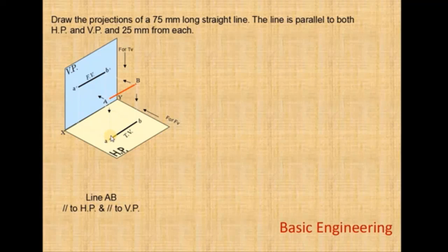And this distance from the HP is 25 mm. The line is 25 mm above the HP. From this line to the horizontal plane is 25 mm. From this line to the vertical plane is 25 mm. The line length is 75 mm. The line is like this.